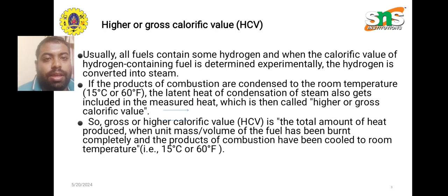Then higher or gross calorific value, which is also known as HCV. Using all fuels which contain some hydrogen, when the calorific value of the hydrogen containing fuel is determined experimentally, the hydrogen is converted into steam. If the products of combustion are condensed to room temperature, which is 15 degrees Celsius or 60 degrees Fahrenheit, the latent heat of condensation of steam also gets included in the measured heat, which is then called higher or gross calorific value.